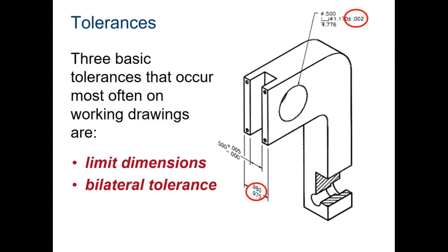It makes a window. And then you have a unilateral tolerance, which says it has to be 0.5. It cannot be smaller than 0.5, but it can be greater by 0.005. So it's like having a threshold on one side that lets you go above, but on the other side you can't go beyond the measurement that you're targeting.